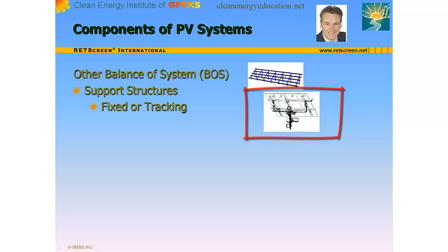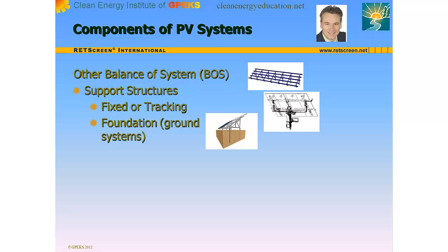They are required for concentrating PV technologies and may be preferred for other reasons. In some contexts, they allow utility scale projects to reach a lower levelized cost of energy. They may also be a better option in high latitude areas where open and cheap space is available. Ground systems may use special types of foundations. An interesting type of foundation is the screw approach that is fast and does not require concrete.